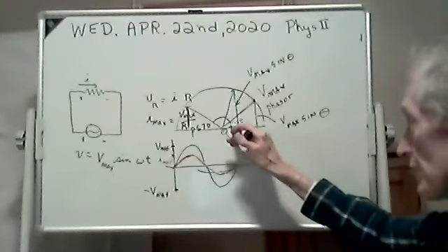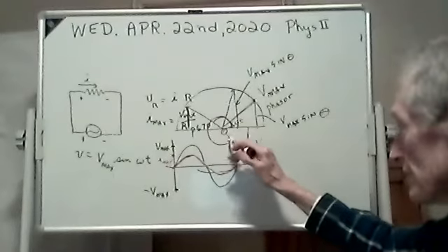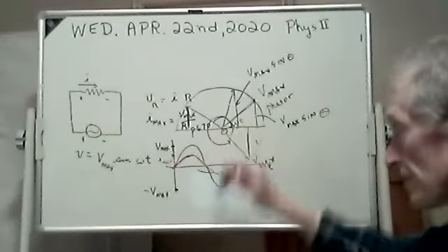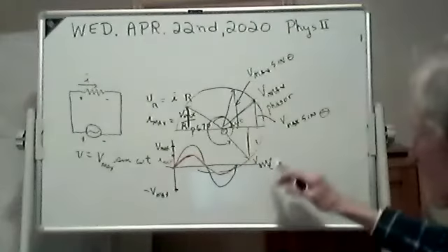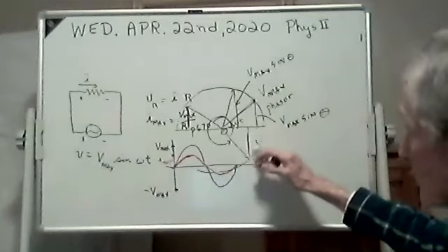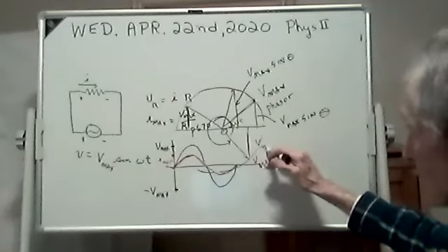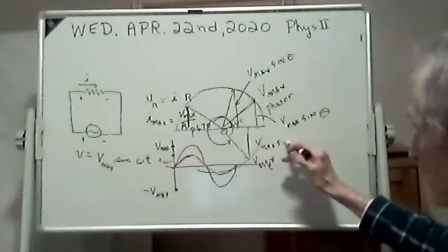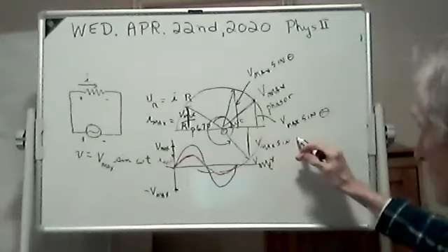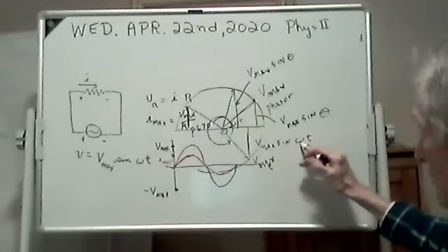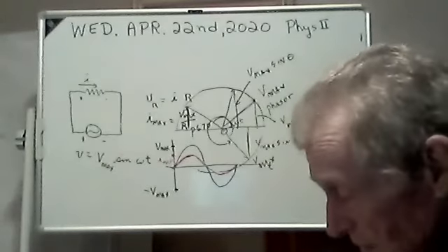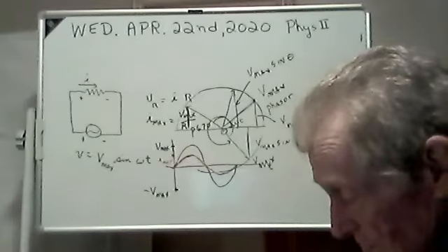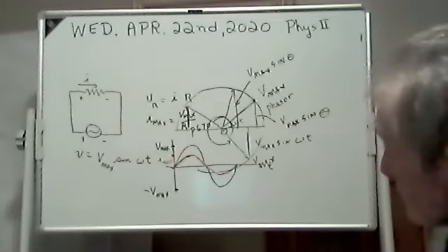I know the angle's really going all the way around, but you could use this angle here, only call it a negative angle. It gives you the same answer. And this distance here is Vmax sine of that angle. In general, it's omega t. Whatever the omega is, the radians per second. You multiply by your seconds and you'll get your radians.